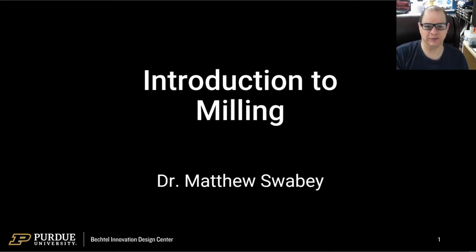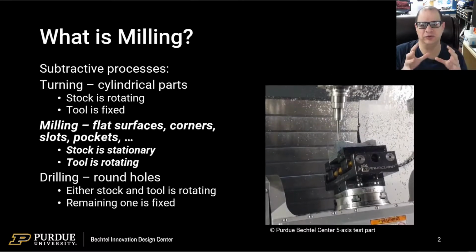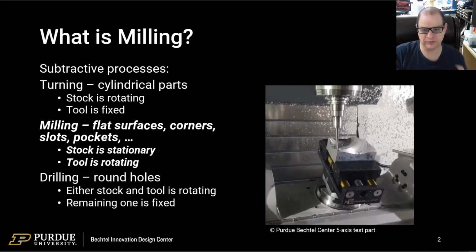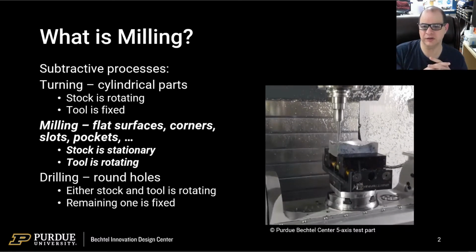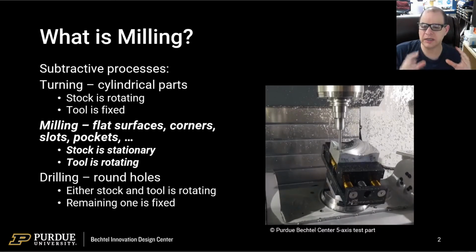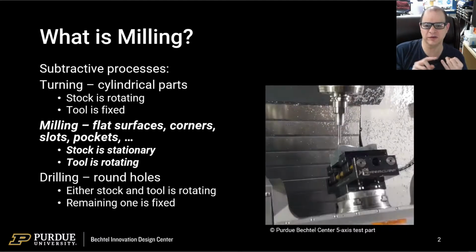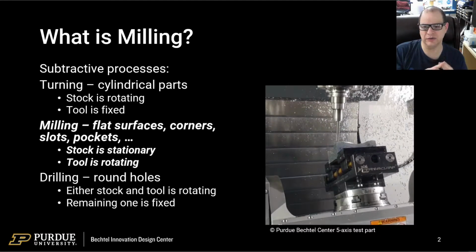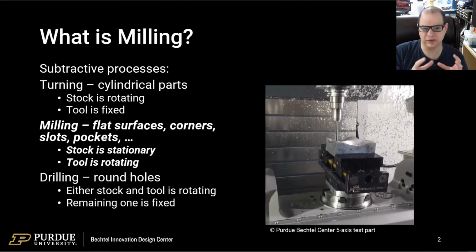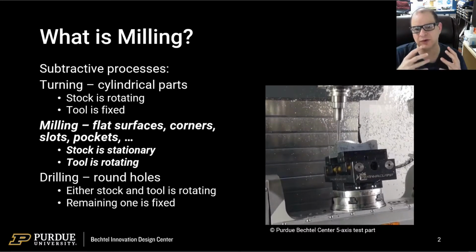Good morning, everybody. This is a brief introduction to the subtractive process called milling. Now, I have a very loose scale, which is not very well defined because machining is too broad a field to be well defined. And in it, I'm classing the three primary subtractive processes as turning, milling, and drilling. Subtractive means start from a large block of material and remove pieces, leaving the actual final design that you want